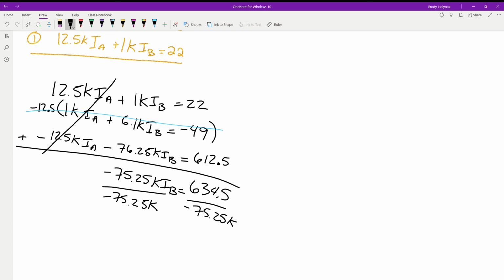Looking at this, what's the first thing that should be going off in your head? Negative what? It's going to be negative current, but we have a negative resistance. The first thing in your head should be, wait a minute, resistance by itself cannot be negative. Resistance is always positive. Nope, it doesn't mean we got it wrong. It just means this value is going to come out negative. So we have our loop drawn incorrectly.